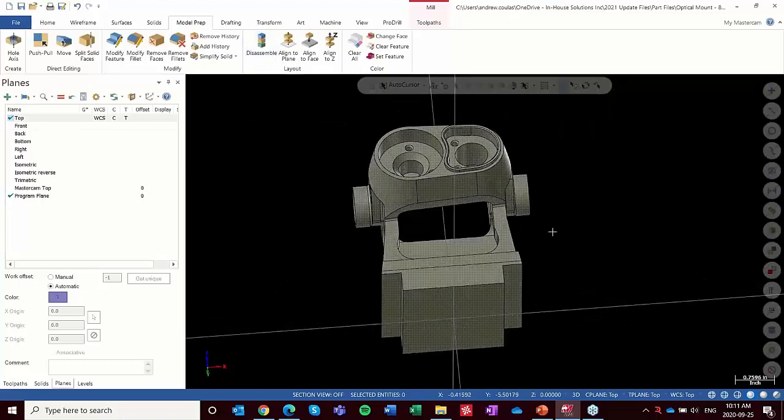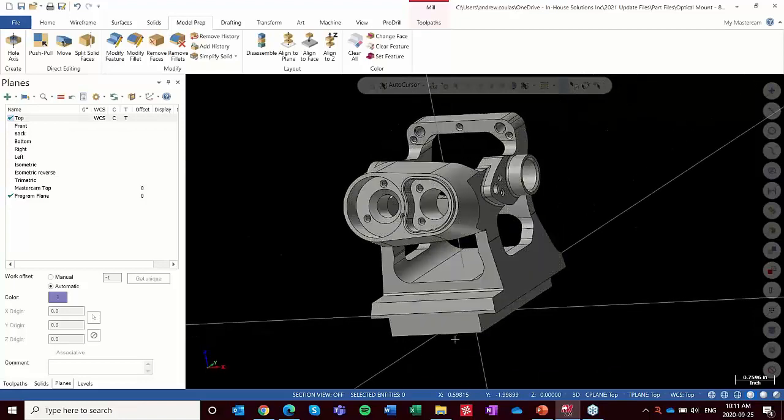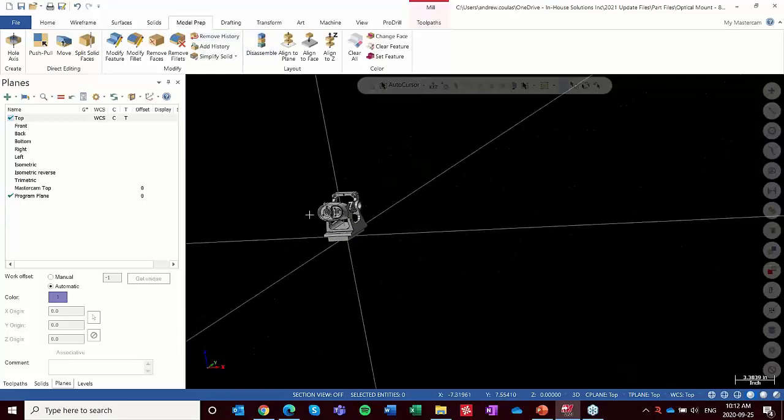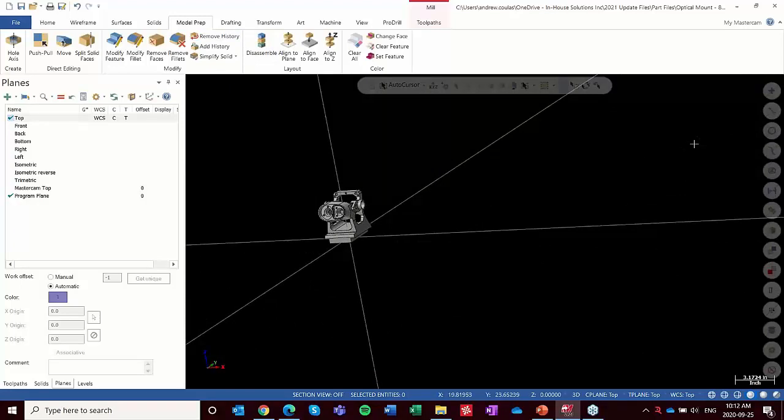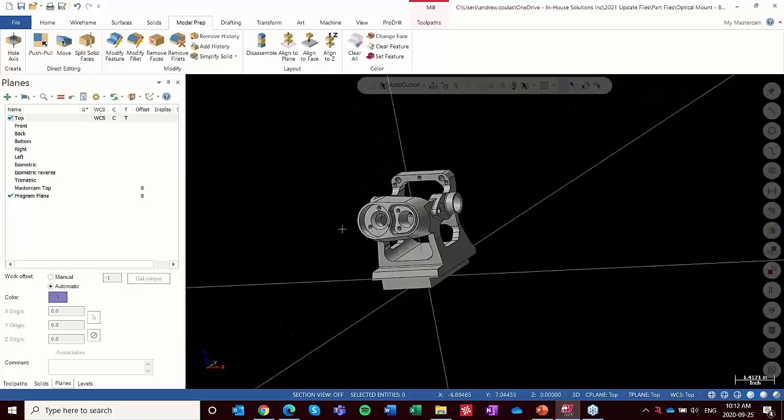So with essentially a single click, I've both moved to origin and aligned it. The only other step I would have is if I wanted this rotated a simple 90 degrees, or if I wanted my Z0 at the top here, I would just have to translate it down to that top point, making my life nice and easy. So in a single step, I've been able to move it from wherever the heck it was in space at whatever orientation to my orientation, aligned nicely to the largest face of the part. So if you ever have that issue where you're opening up files and they're here, there, and everywhere, you can, of course, feel free to do that.